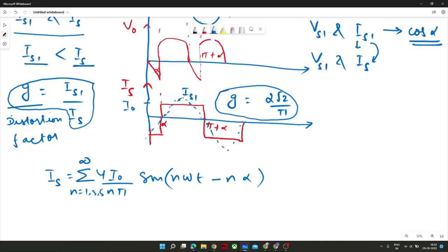So it kind of tends to provide us a square waveform. Anywhere you can see that, or maybe at some point of time, I would take one session on simplification of this kind of series, this kind of waveform, where there would be some tricks or ways to calculate the Fourier series. But I think you would be aware that for this kind of square waveform, the peak value magnitude is multiplied by 4 by n pi sine omega t.